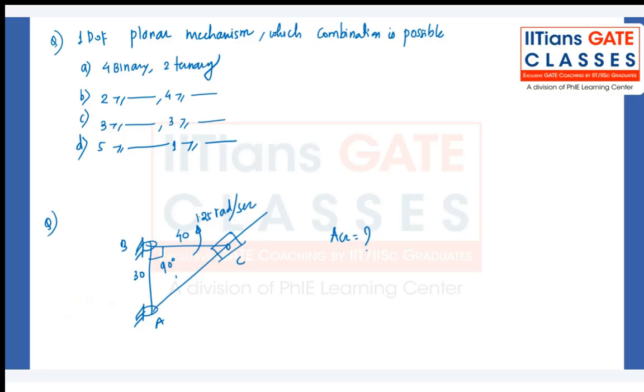They have given you the angular velocity of BC, and yes, you can use this, but they have not given you the velocity of the slider. Your Coriolis component of acceleration is 2v omega. They have not given you the omega properly either. You need omega of the fourth link, omega of AC, and the velocity of the slider. Nothing is given, so this is also a good 2 mark question.